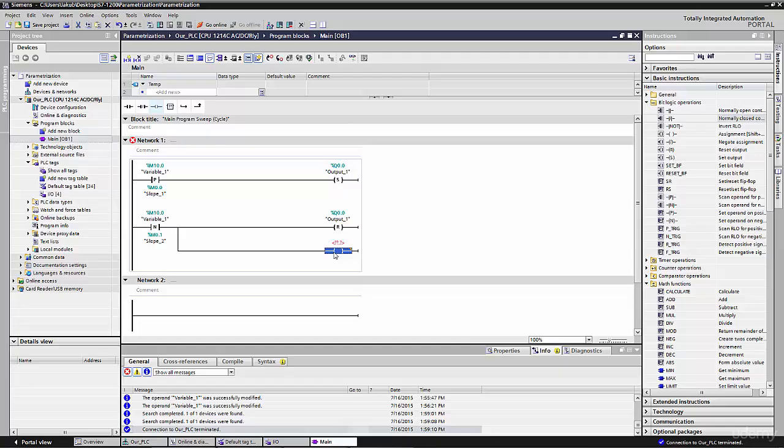It cannot work at one time with these two coils, because you will always have a problem. So you should use the open coil only once in the program, never twice. The set and reset coils you can use many times in the program, it's not a problem.